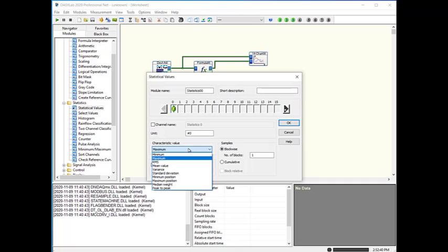So what I'd like to do for this example is set up statistics to do 5 different computations. Add 4 channels so that you've got 5 total, 0 to 4 are defined. Channel 0 is going to be minimum. Channel 1 will be maximum. Channel 2 will be the RMS. Channel 3 will be the mean. And channel 4 will be peak to peak.